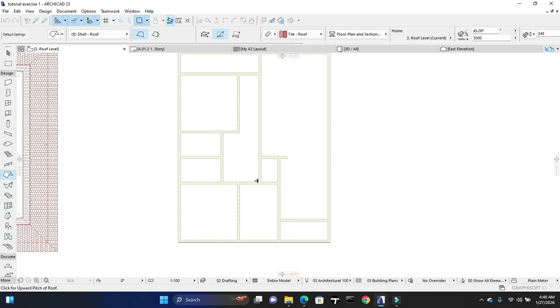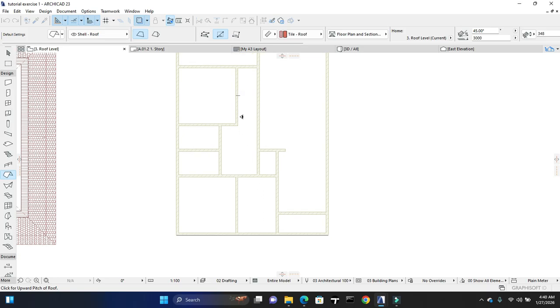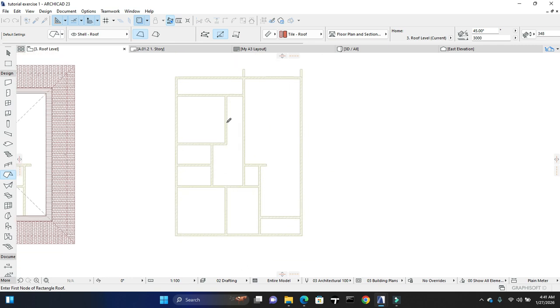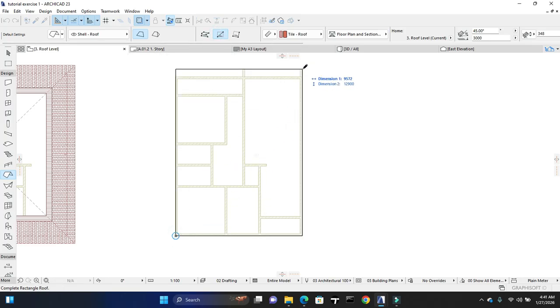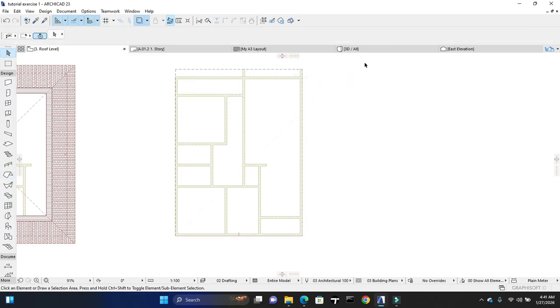Now this is how high the roof is, because I didn't set it properly. So to set it, I have to select the roof, go to settings, make sure that it's starting at roof level, and delete these numbers to 0. Now it's still very high because the pitch is just so funny. So let's change the pitch to, flat roof is usually flat, so probably 15 or 10.